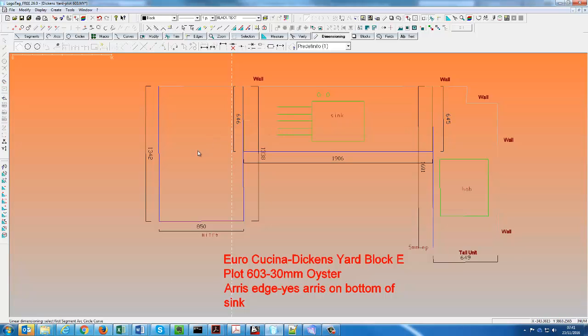Next, and this is the bit that you guys are getting a bit confused on, is you click on this button here, more elements, and it's a case of using these snaps correctly, because at the moment I think you guys are just basically guessing where the dimensions are and hoping for the best. That's not how this works. In CAD you never guess.